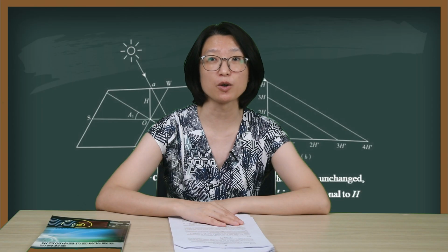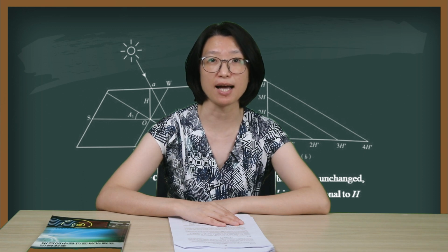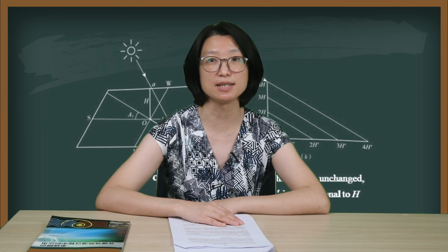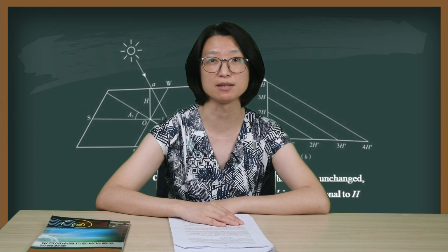You can use the calculation method to check whether the building spacing of the school building meets the sunshine standard, and then try the school building in another location. You can also check whether your architectural design work meets the sunshine standard. Think about the reasons why the same type of building adopts different floor spacing in different locations. What happens if the building is not facing due south?